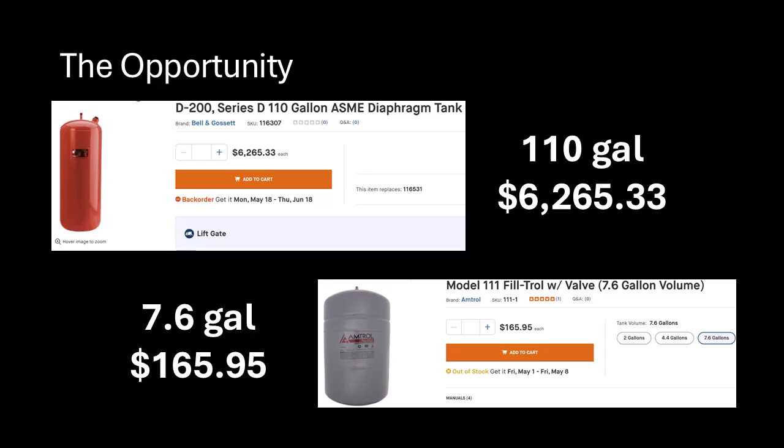In geothermal system design, we've inherited a conservative habit from the hydronics industry, treating every pipe like it's made of steel. But in a large-scale HDPE loop field, that assumption leads to oversized expansion tanks, increased project costs, and wasted mechanical room real estate. Why? Because it ignores the dimension of time.